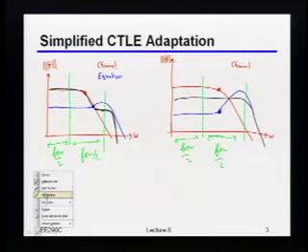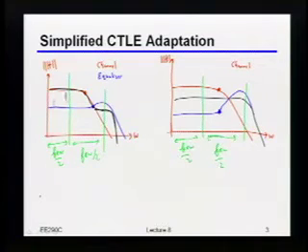In the left-hand case, when I haven't adapted things properly, it's pretty clear that I'm going to have a lot more energy in the lower half of my bandwidth than in the upper half, because in the upper half I've got that roll-off that starts happening. Whereas over here, when I've adapted things properly, in the lower half I should basically have the same amount of energy as in the upper half. Now, when I say half, it's not necessarily exactly half, because remember, I don't put the pole at exactly the Nyquist frequency, but at least conceptually, you can think of things that way.